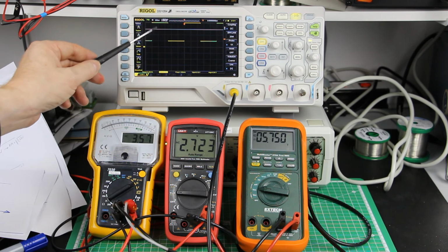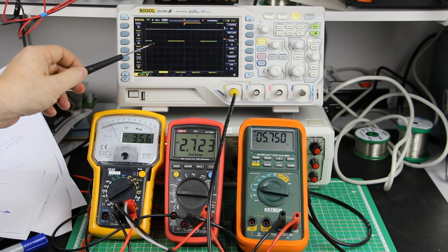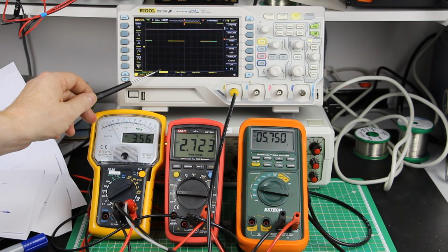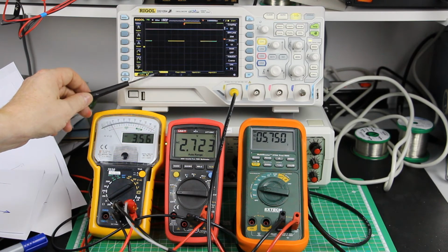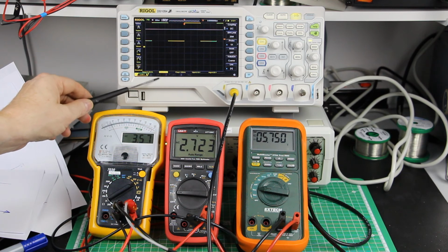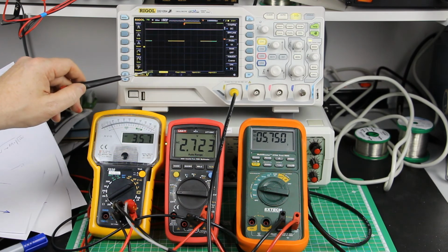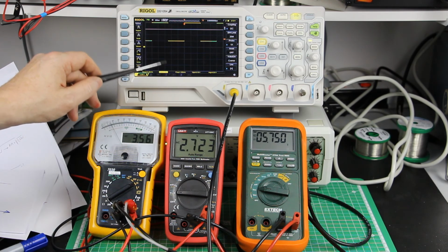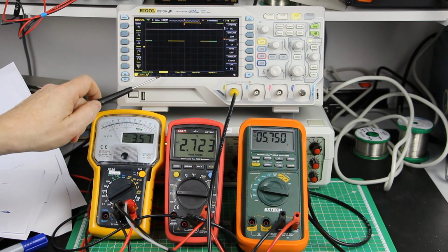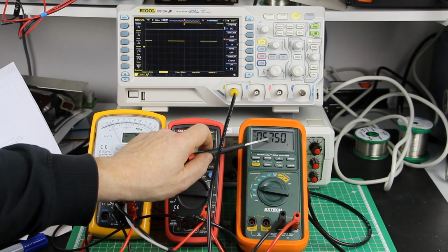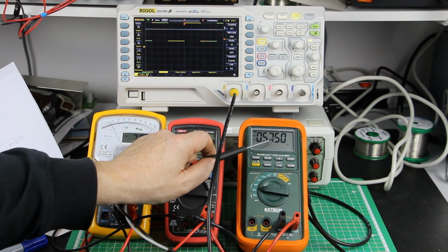enough for a comparison. And the nice feature that every modern digital oscilloscope has, it can calculate the true RMS value of any waveform and of any frequency just with its internal processor. And we get here an RMS value of, it jumps around a little bit. You probably won't be able to read it due to the resolution of the camera. It jumps around 5.76 volts, and that's within 1% of what the X-Tech